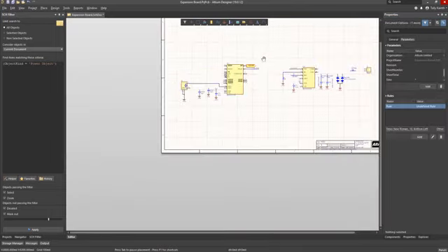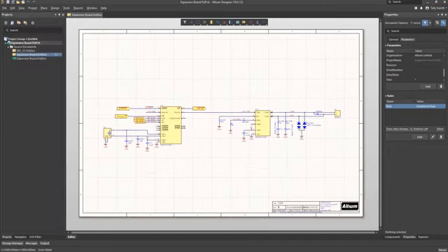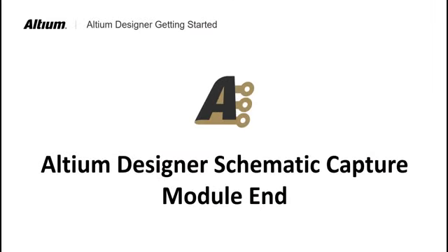We would continue to add wires, net labels and ports as needed to finish the design capture. This is what our design would look like at this point, with everything wired, ports added and nets labelled. This would be the entire design. We can also add text strings to the design to identify the 3V3 and 5V sections of logic using the place, text string option and hitting Tab to edit the comments before placing. This completes the part placement, wiring, net labels and ports needed for the design. In our next module we will compile the design.